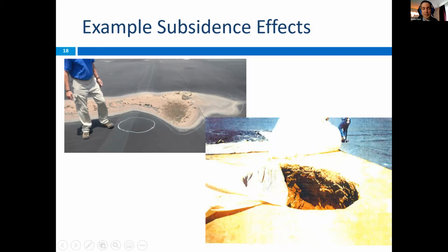But I think a more frequent occurrence, and more troublesome for long-term performance, is actually a case like this, where you can see there's an accumulation of silt on the exposed geomembrane that indicates that we have a low-lying area where water is not able to successfully drain. If this were allowed to continue in our final cover, then we would have, for years and years, ponding water over this location with the possibility to infiltrate through holes. So this is really the thing that we are focused on trying to prevent. This is probably the most pervasive problem that we're looking to address.